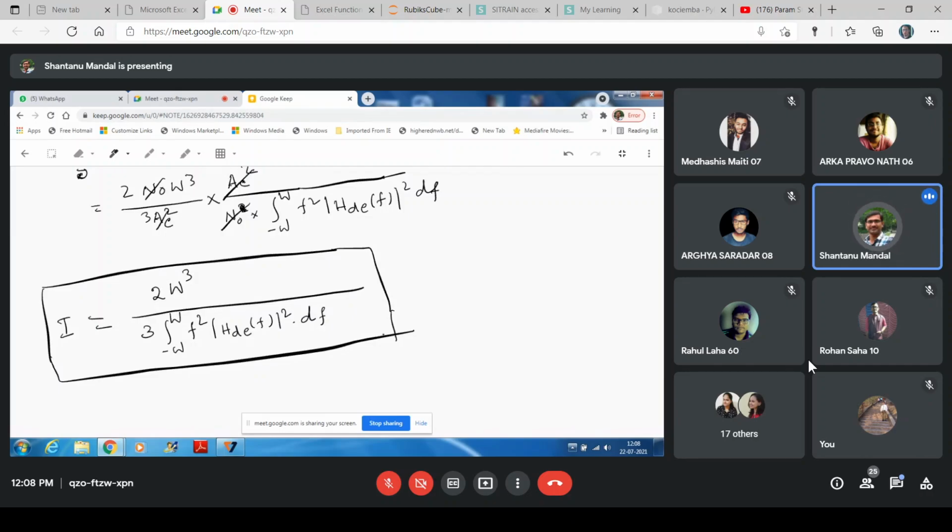What is the pre-emphasis, de-emphasis filter? Now this is nothing but a filter which can artificially boost up the message signal at high frequency, because you can see that at high frequency the power spectral density of the message signal is low, but the power spectral density of the noise signal is high. As a result, some more distortion occurs at the high frequency in the FM receiver.